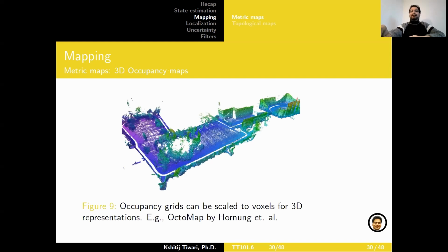Okay, now, as I said, one might easily argue that navigation of a robot in the real world could easily require a 3D representation of the world. For example, a drone is flying in the air in an environment, even if it is an indoor environment, but there is some height of the obstacles, there are walls which have a height, there is some depth. So we require some sort of 3D information, but that's not possible if you're talking about occupancy grid maps in 2D, right? That's just like a flat floor plan.